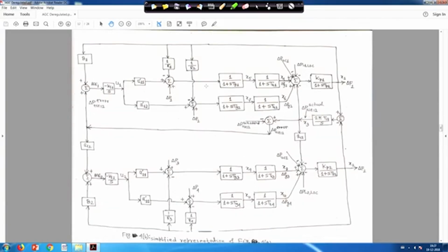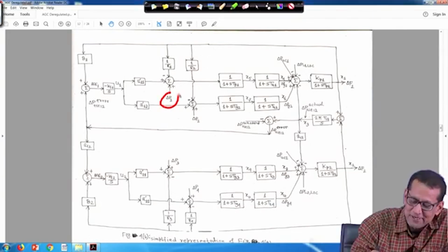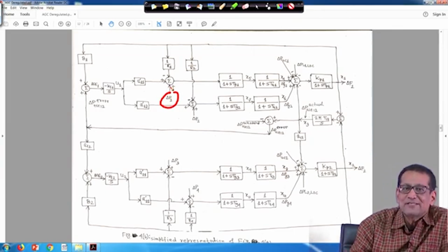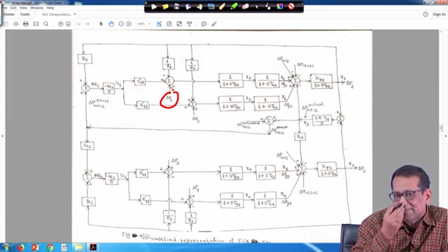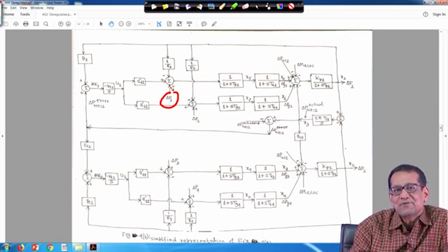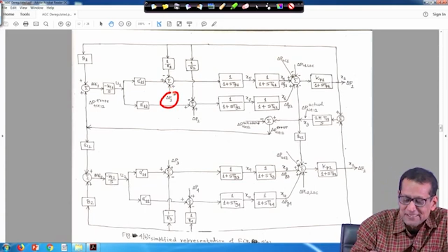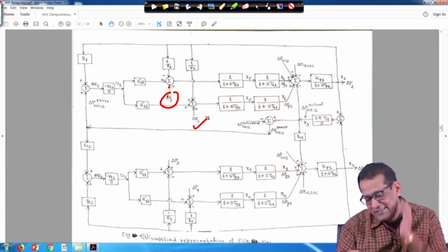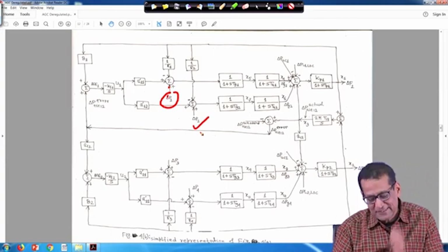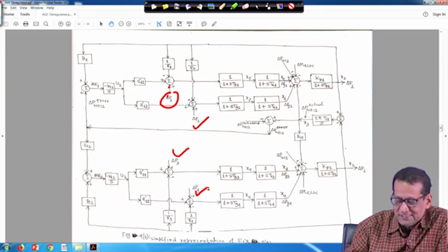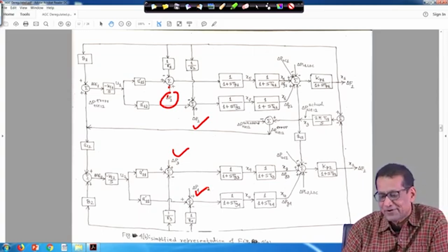So, ultimately, whatever I told you, here you have to give an additional input, that contacted power. So, delta PL1 is CPF 11 delta PL1 plus CPF 12 delta PL2 plus CPF 13 delta PL3 plus CPF 14 delta PL4. So, that is here coming as GENCO 1, right. Similarly, delta P2, because all these things are summed up and put here, and similarly for GENCO 3 it is delta PL3, and GENCO 4 it is delta P3 and delta P4, right.